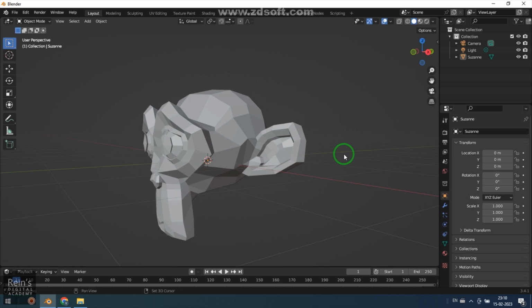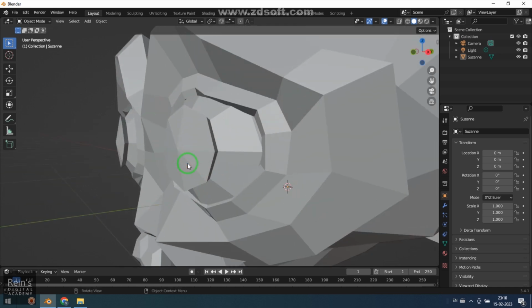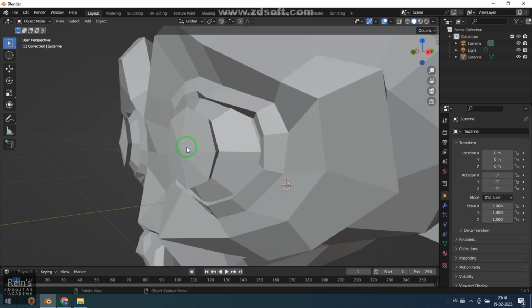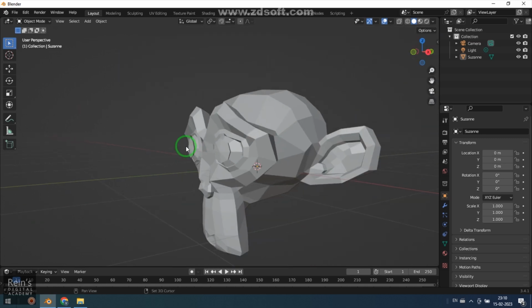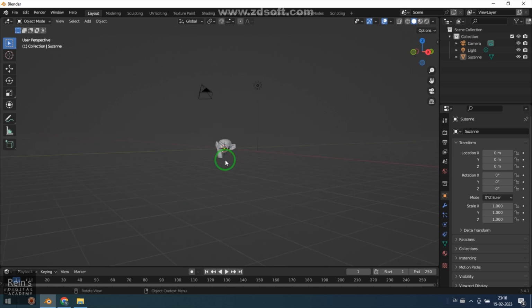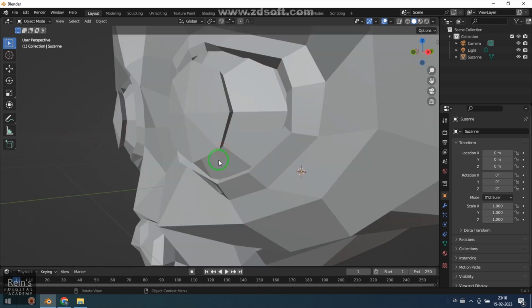You can press Shift B, then you get a cursor. Just drag onto one particular area, and you can zoom in to that area. Shift B again, this time use the middle mouse button, and you zoom out. Shift B, zoom in with the left mouse, sorry.